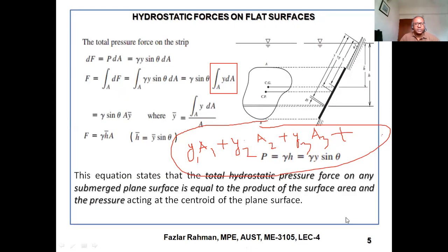You remember that X CG equals the sum of area A i times X i, with i equal to 1 to n, divided at the bottom by the sum of areas, meaning the total area of the whole object. Then you take the summation. Do you remember when you figured this out?